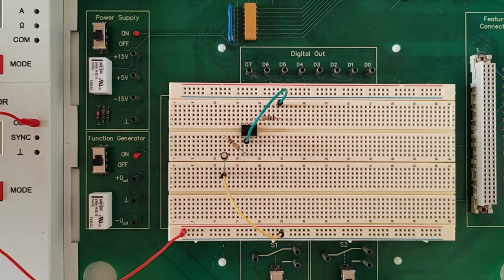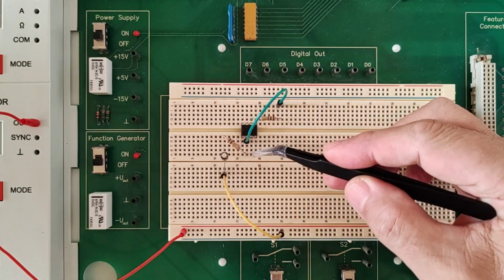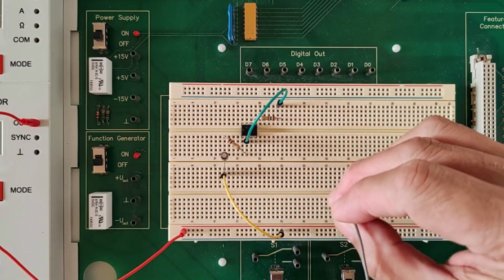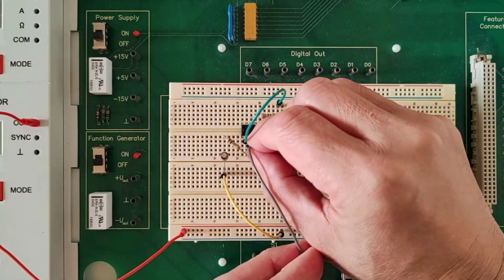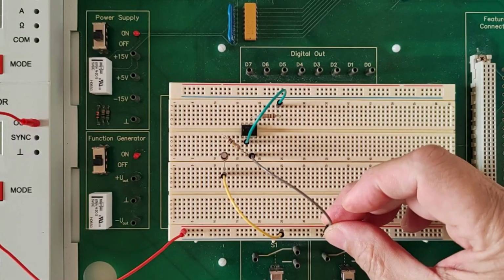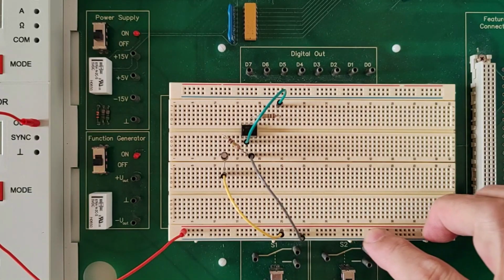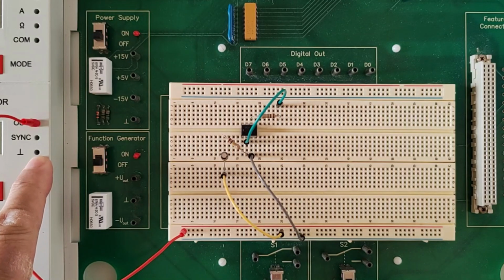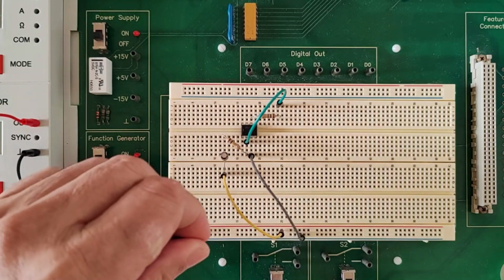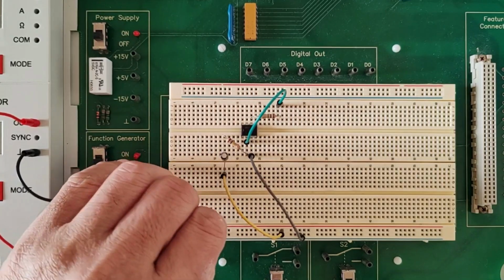Now, pin number 3 of the integrated circuit needs to be grounded. That's our non-inverting input. So the non-inverting input, pin number 3, I'll ground it using a jumper wire. I'm going to put the jumper wire here on the bottom blue rail because it's closer. And since that is ground, I will connect another power cable coming from the ground pin of the function generator to the blue line at the bottom, like so. There.